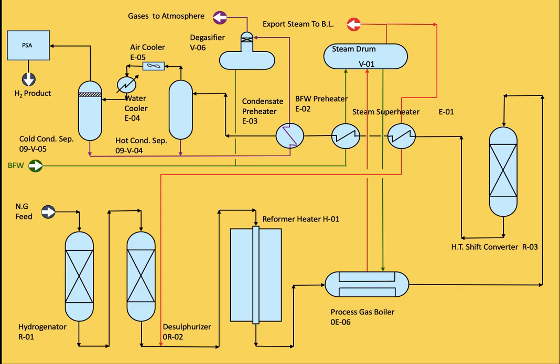Okay, what is the space velocity related to this type of reactor? It is between 1000 to 3000 per hour. As we know, the liquid hourly space velocity unit is per hour. Okay, low space velocity, high conversion. Low space velocity in this reformer equals high conversion.